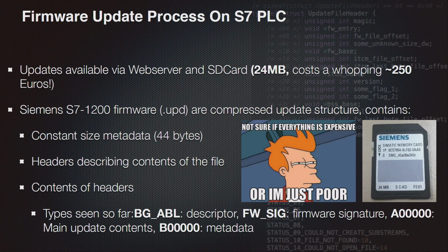The other way you could update the firmware, by the running firmware itself, is via the web server, where you can upload a chunk of your firmware update, and it will check different firmware signatures, or one firmware signature over a hash, which is a secure update mechanism, where I think no real issues were found. So the firmware side of things performs an integrity check and also makes sure that this update comes from Siemens, if we are aware that Siemens indeed is the only one who holds the private key, which we, of course, assume here.